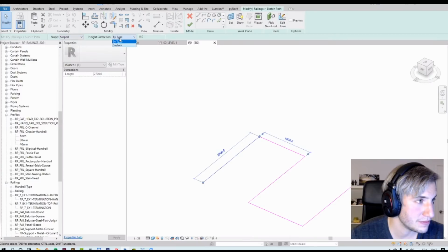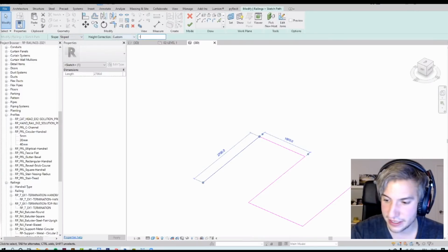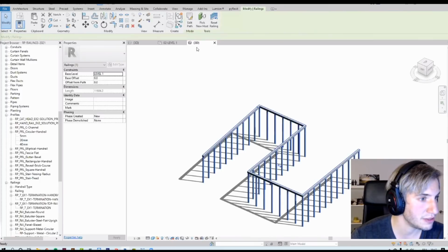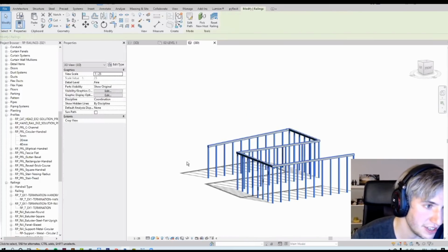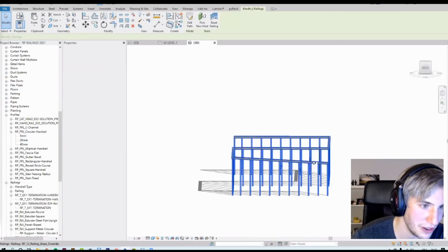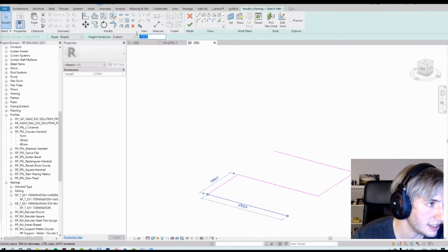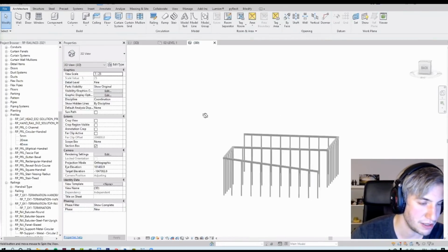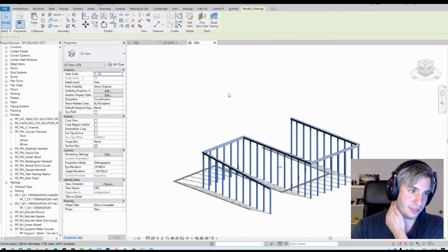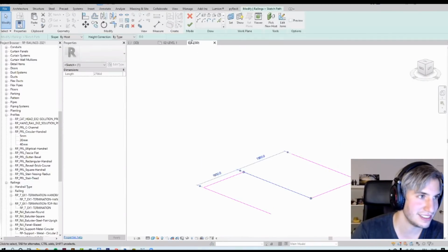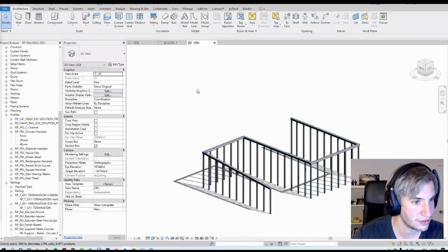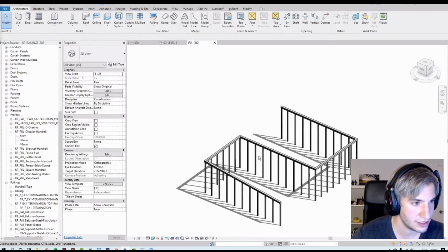And that's the slope of the rail. So the base is going to stay the same, it's the top rail. So let's say I set it like this. Let me show what happens. As you can see, I just created a small slope only on this segment. So let's say I put minus 300 like this. So now it's a little more obvious. Wow, that is cool. I had no idea. That's another one of those things that I can see being useful for things even beyond just railings, when you're using railings for other things.